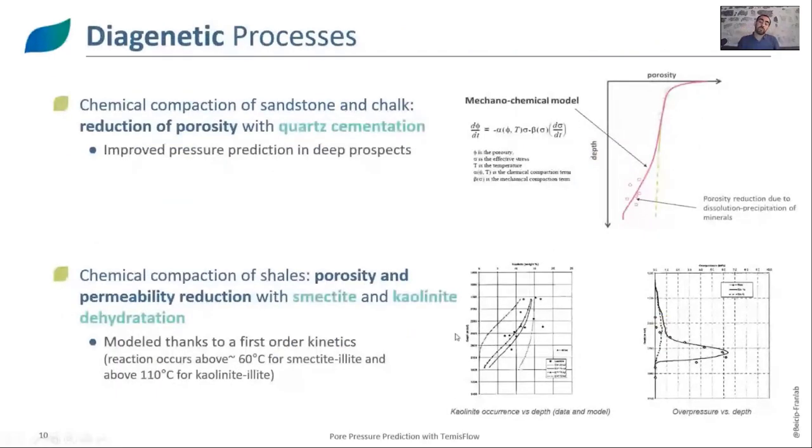So these were the main driving factors, but you can of course take some much more advanced phenomena into account when trying to quantify the pore pressure within a basin. Here, let me present to you the diagenetic processes that can be handled within TemisFlow. We can take into account diagenetic processes on sandstones or shales. For sandstones, we take into account the quartz cementation, which is this law. Where you will first define a purely mechanics-driven pressure curve, and all the chemical aspects will be computed through this equation, where you will have precipitation and cementation of quartz.